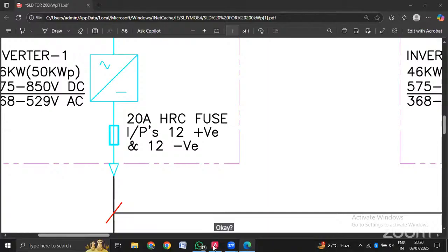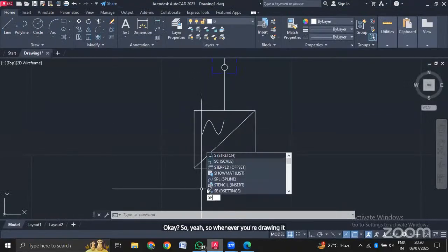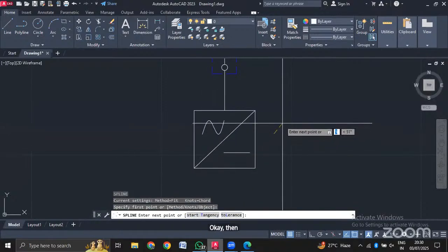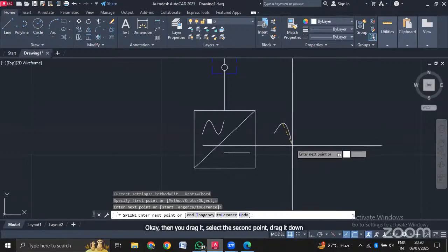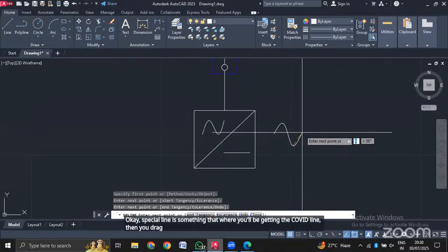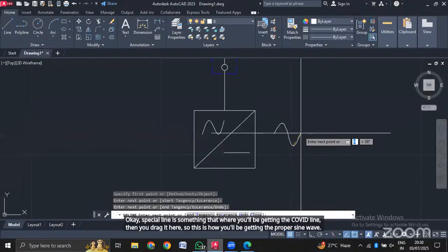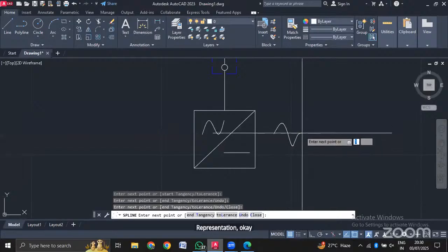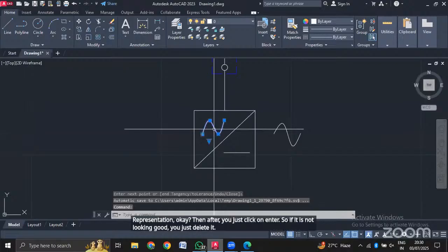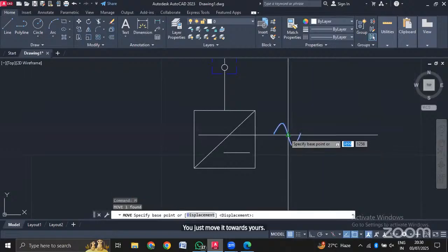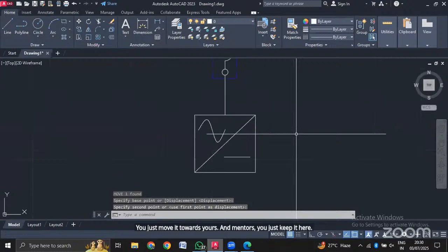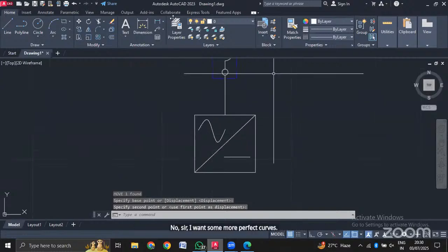So whenever you are drawing it, simply use SPL, enter, select the first point, then drag it, select the second point, drag it down. The special line is where you get the curved line. This is how you'll get the sine wave representation. Then you just click on enter. If it is not looking good, you just delete it, or move it towards here, enter, and keep it here. But if you want some more perfect curves here...